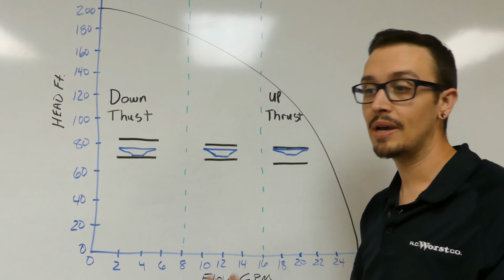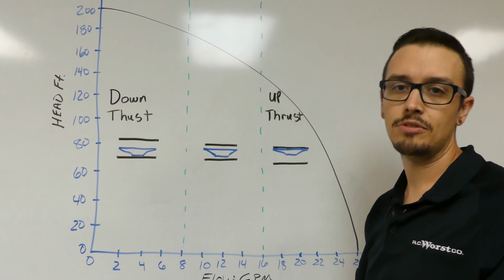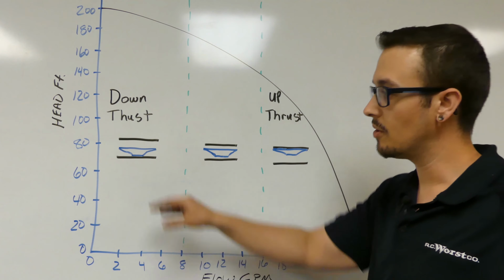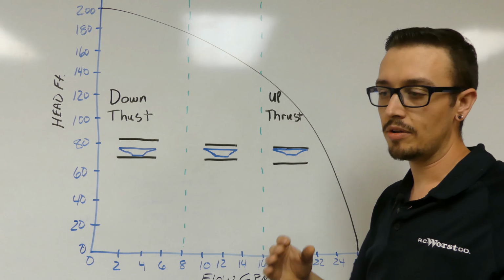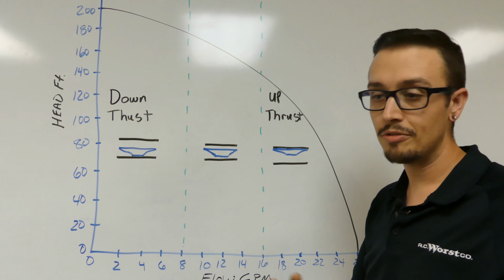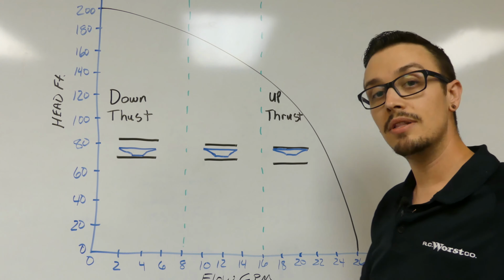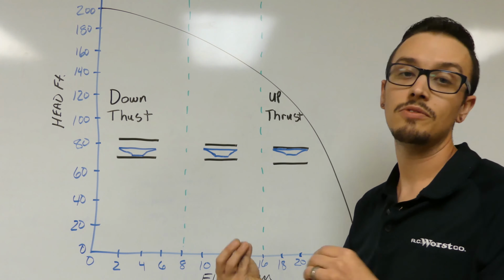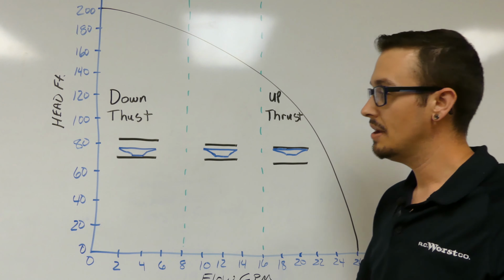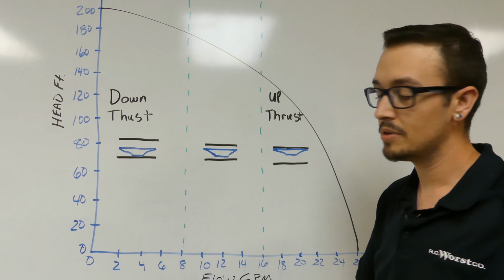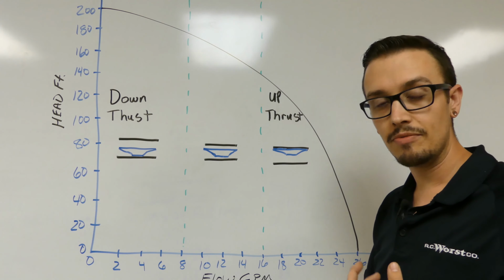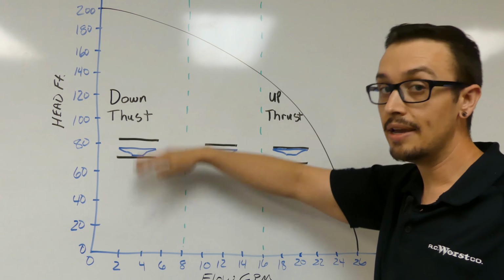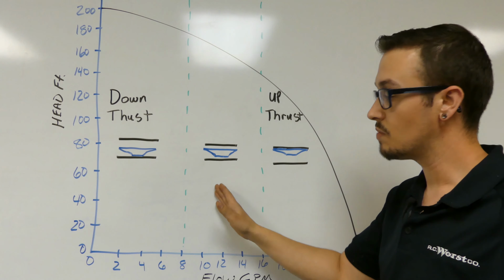The trade-off to that, you might think, well, how about I just use stainless steel impellers that are fixed in place? Oftentimes, with pumps like Grundfos, you don't have the same type of setup where the impellers float or move up and down. They're more fixed, but that really limits your solids handling capability, more in terms of volume of sand as opposed to size of the solids. So a good sand handling pump is going to have glass-filled reinforced plastic impellers, and it's going to have a little bit of play in the up and down, and that's why they have this recommended operating range.